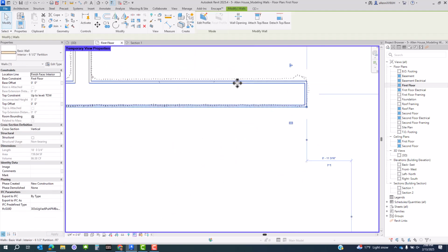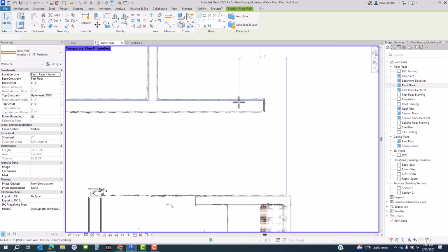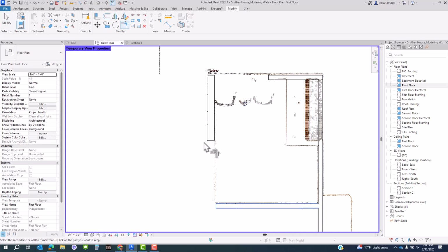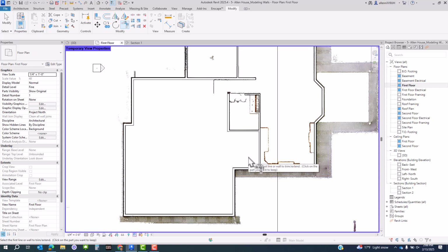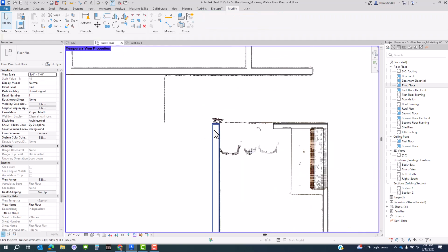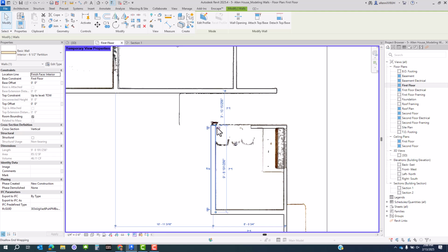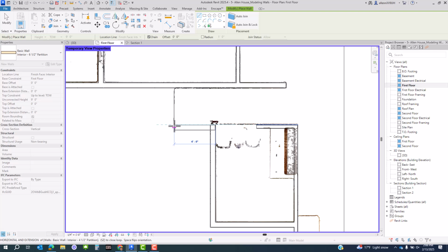And that does seem to fit within the thickness of that wall right there, so I don't think that I do need a different wall thickness. Okay, in my mudroom, I know that you can't see it and you didn't see it, but it does something like this. And actually, I believe this part is garage, so that should be a 6-inch partition right there too. And then I guess I got to think about this. We'll just draw a wall back and then forth again, like so.